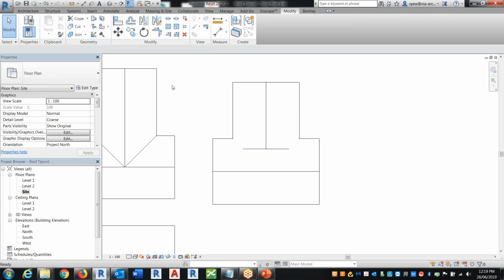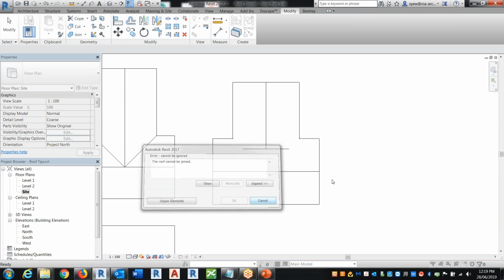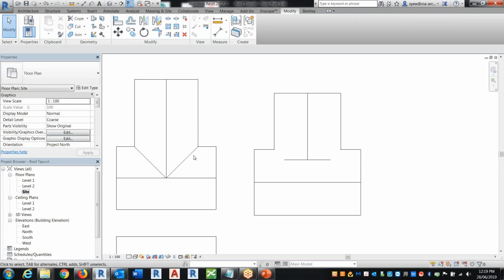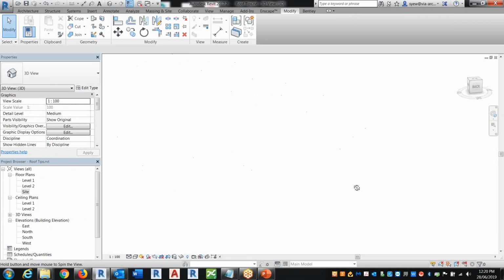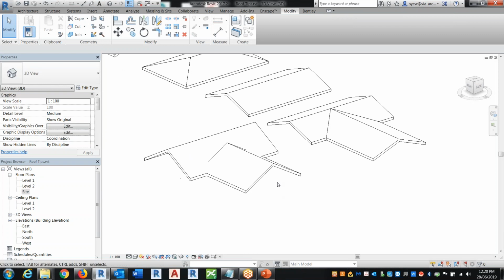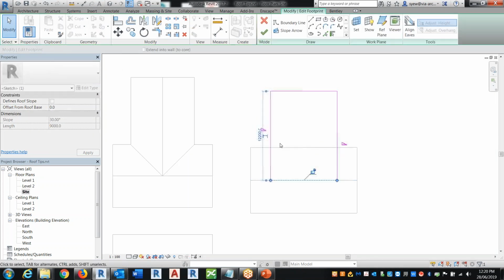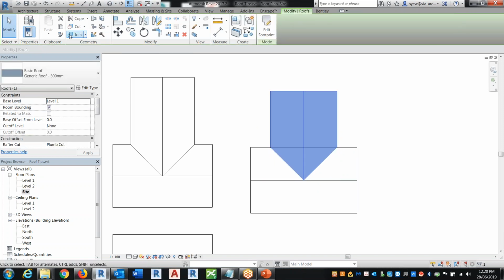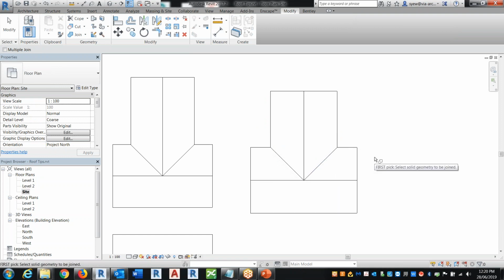Most cases, it works. All you have to do is select the surface, select this, and it will just join itself. But this one, for some odd reason, just doesn't want to do it. Last time I tried, it looks like this. But if you do get frustrated, which I understand, what I typically like to do is, you don't care about what's going on at the bottom. Just join it. Just use the join geometry. Join geometry works perfectly fine.